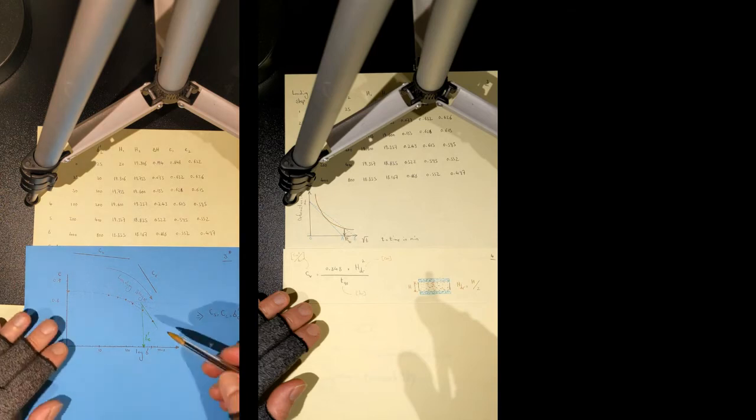And then you have a part which will kind of tell you that small amounts of variation in effective stress will cause tremendous amounts of void ratio loss. This is the normally consolidated or virgin line, or the normally consolidated state of soil, which kind of tells you that the state of soil here is pretty much weak.